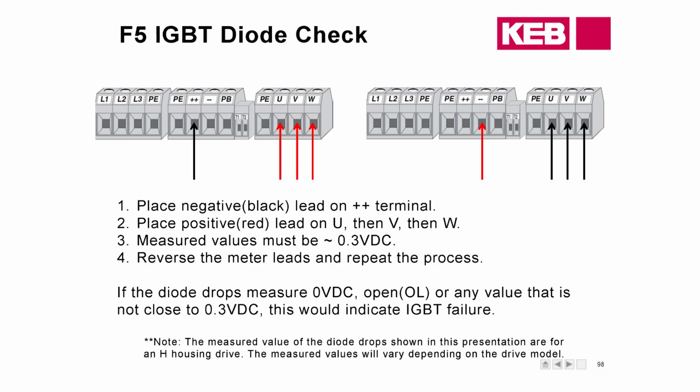So what I want you guys to do is take your black lead from your meter, put it on the plus terminal, and then take your red and go to U, V, and W, and tell me what you get on each phase. 0.1. Yep. What's the short? What's the transistor?